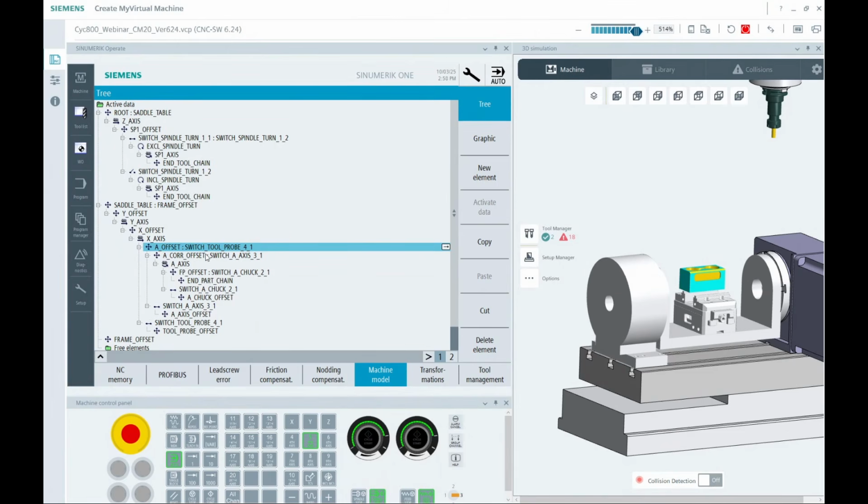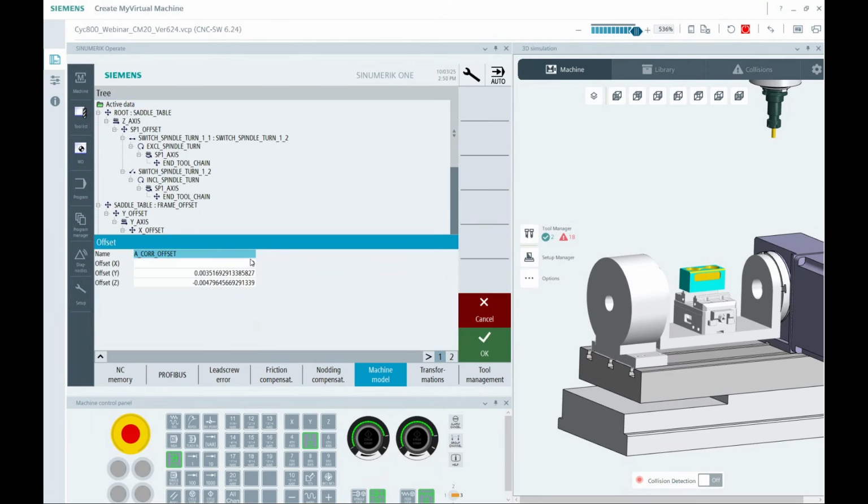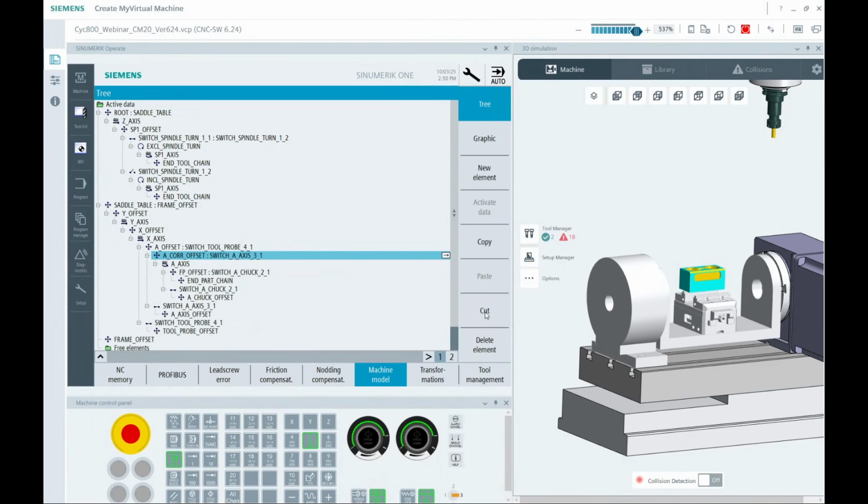But when I build it, it's never going to be exact, right? So I could use the base value of, say, hey, CAD thinks this is going to be 17 inches down and 6 inches over. In the real world, it's maybe another 30 thou, 40 thou over. You would write that into the correction offset. So those would be the two different scenarios that you would start to see from a configuration standpoint on your machine.